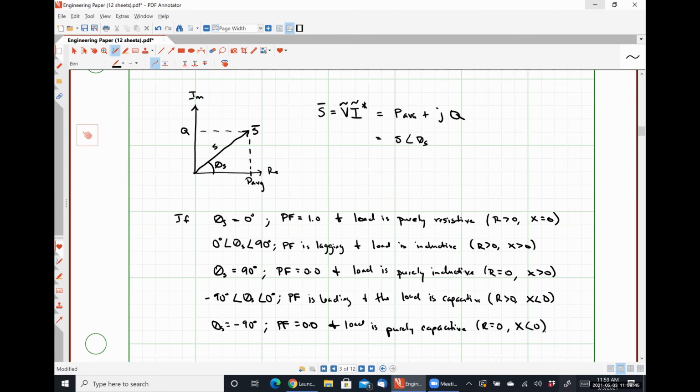Now you would think that because those resistances are that small, they don't really come into play, but everything in an integrated circuit forms an RC network, because even just a section of wire forms a capacitance with a substrate, which means that everything is fed through a low pass filter. And so even those very, very small resistances start to matter because they limit the switching speed of your transistor architecture and all that kind of stuff. They'll come and bite you quicker than nanosystems classes if you're not paying attention, I guess is what I was getting at.